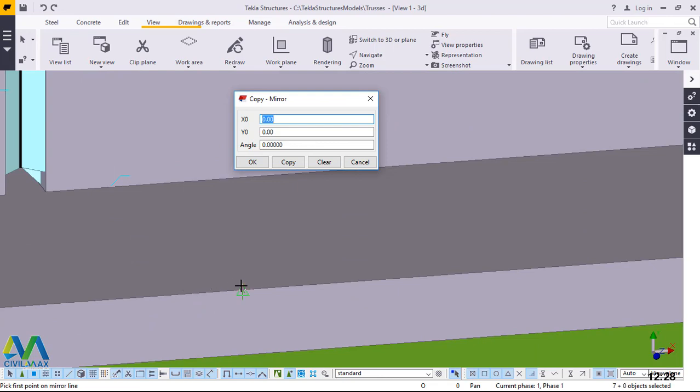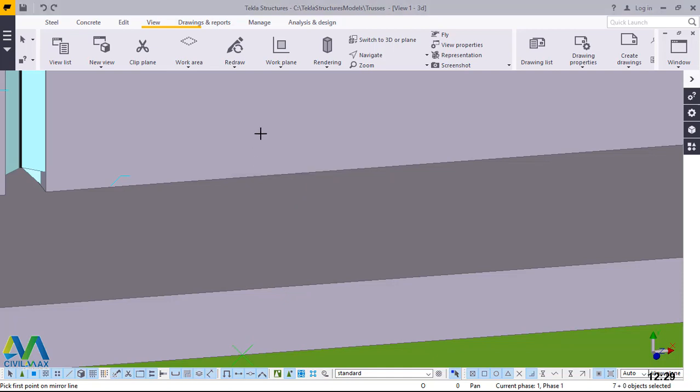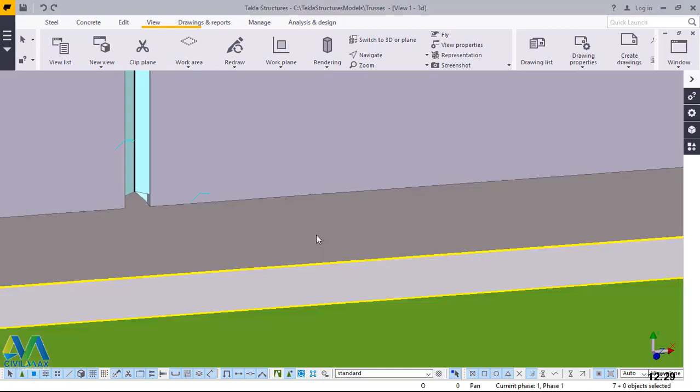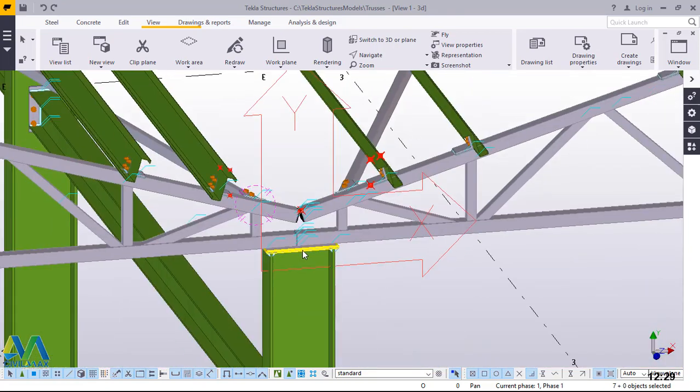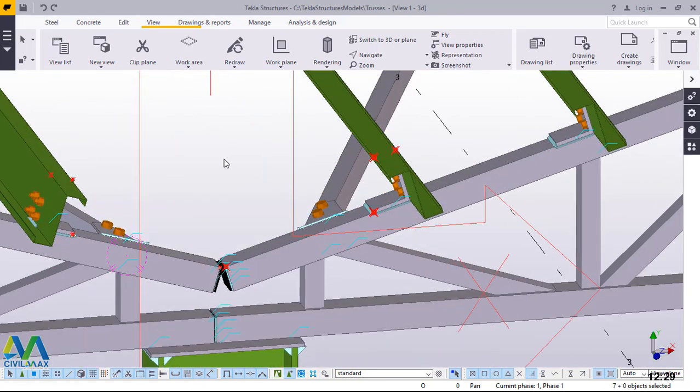from this plate, from the midpoint of this plate. I'll snap right here and snap on a straight line right there. You can see the angle is 90, and click OK and give it an acceptance by clicking an OK button. Click interrupt to terminate that command. Now if we zoom it out, you can see the points have been mirrored to the other end, this end.